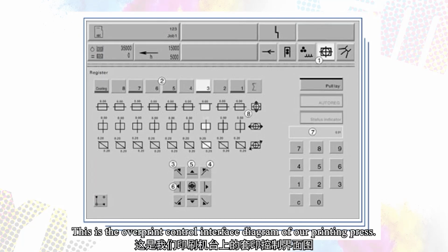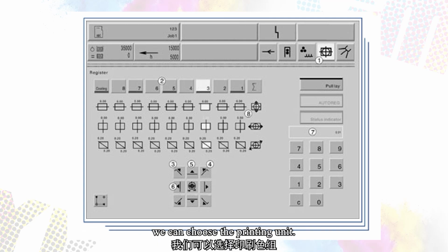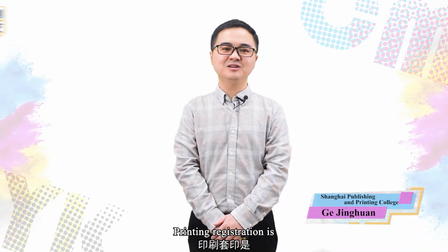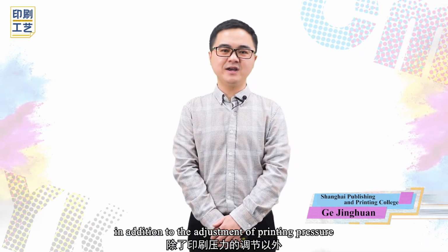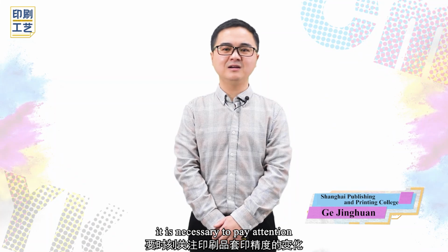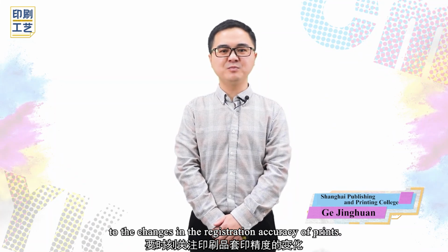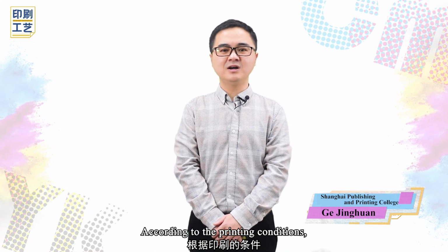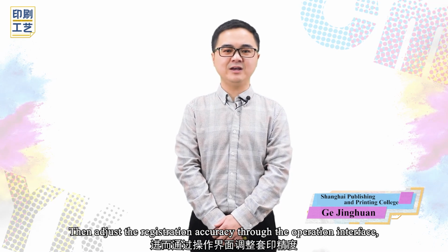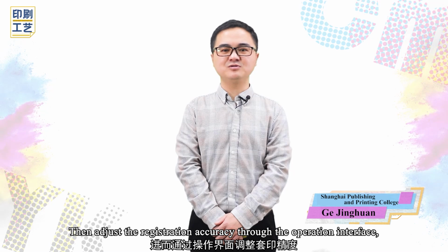This is the overprint control interface diagram of our printing press. Via the buttons above, we can choose the printing unit and adjust horizontal, circumferential and diagonal registration accuracy. Printing registration is, in addition to the adjustment of printing pressure, another very important regulation process. In the printing process, it is necessary to pay attention to changes in the registration accuracy of prints. According to the printing conditions, analyze the causes of misregistration, then adjust the registration accuracy through the operation interface.